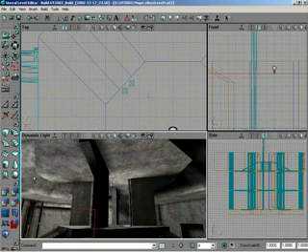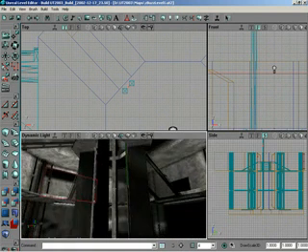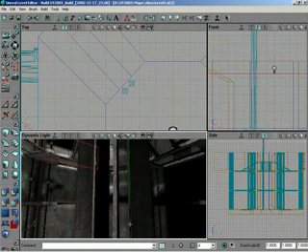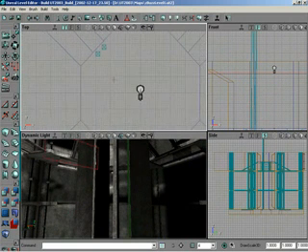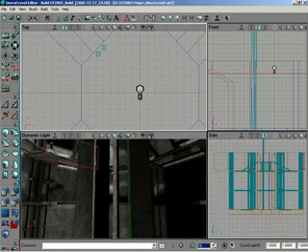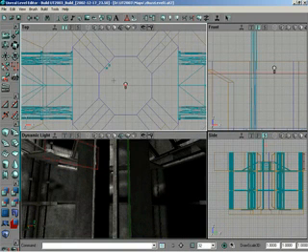Excellent. So with all those, I'm going to go down and using Control, grab and reselect all of those. And the last one, so we have all 4 of those selected. Now in my top view, duplicate, center it up, and let's see here. Let me set my grid setting to something else. So let me slide it all the way up to 32. That way I can center their pivot, and then I can rotate them around to another pillar.